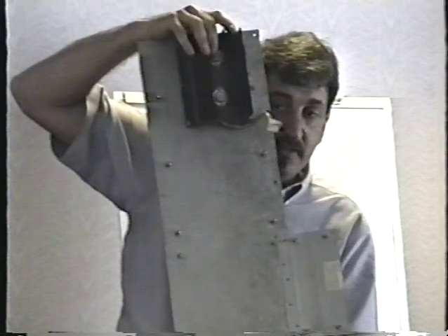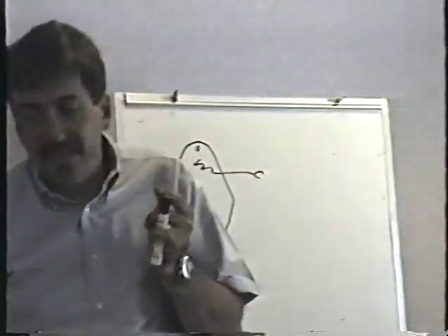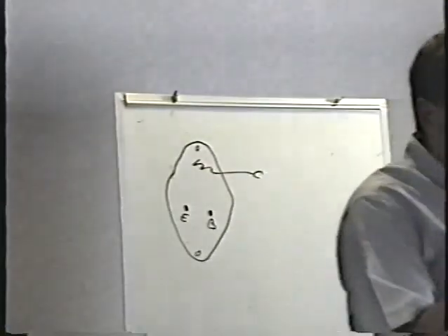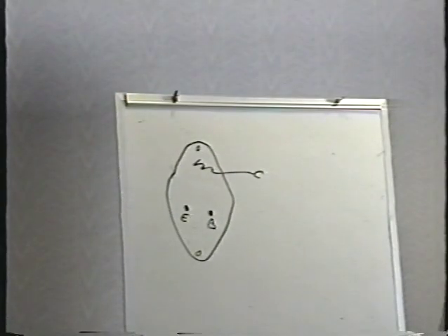Whenever you see transistors mounted on heat sinks, you'll see these insulators mounted behind them. Don't mess these up. I'm just going to pass them around so you can look at them. I only have 4 of them here, so be careful with them. These are made out of mica. They're fairly delicate, so don't screw them up.